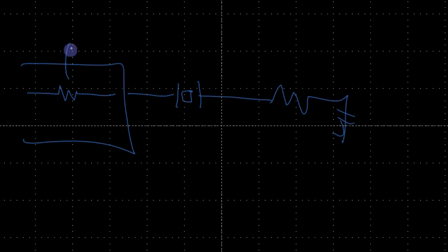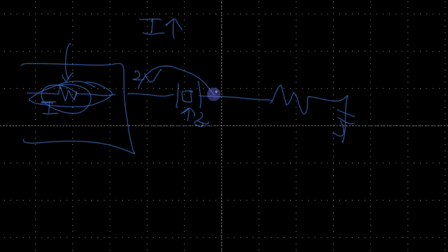One reason the voltage drops is that at the resonance frequency, the current is the highest, obviously. And when the current is the highest, current has to pass through this internal resistor, or what we call output impedance, so voltage drops across this. So we don't get that full 2 volts.